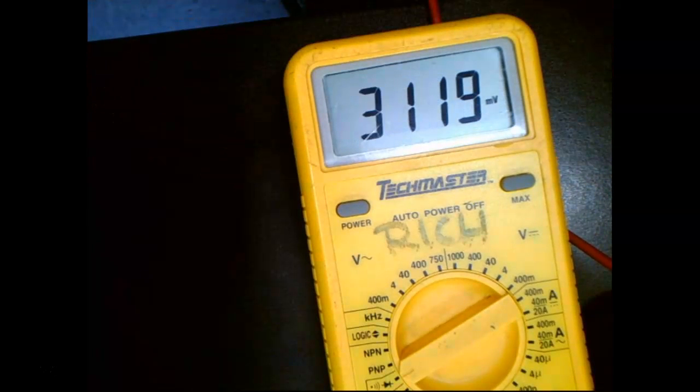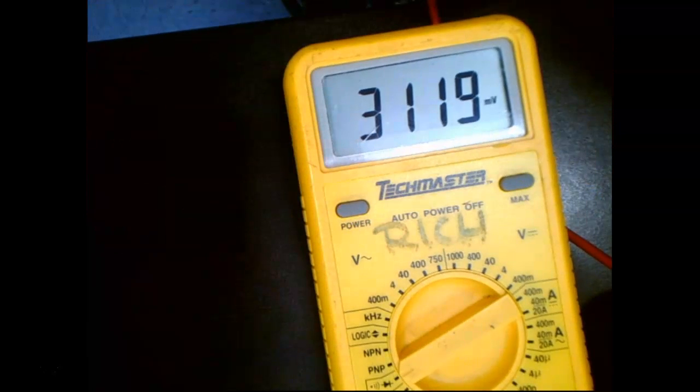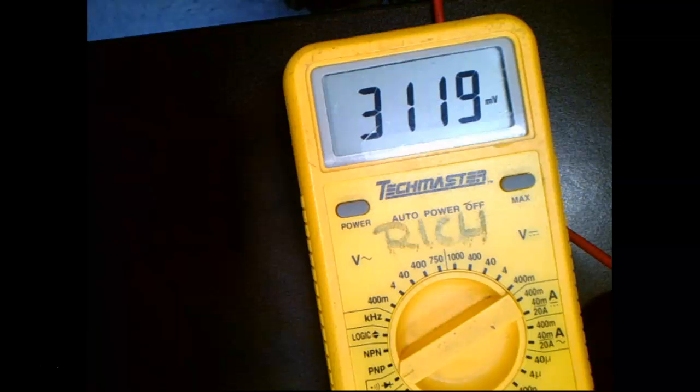And it's measuring 727 millivolts. And then when I reverse bias it, it's measuring what my meter measures when it's open. So what type of diode is this? Is it silicon or germanium? Is it good or bad? It's good, right? Because it measures right. If it measures the same thing in both directions, it's bad, right? If it measures 0 or anything like that, it's bad, right?